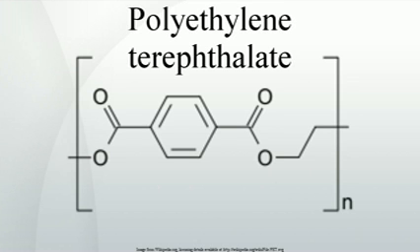Results are decreased reactivity during repolycondensation or re-SSP and broadening of the molecular weight distribution. The end group proportion shifts toward COOH end groups built up through thermal and oxidative degradation. The results are a decrease in reactivity and an increase in acid-autocatalytic decomposition during thermal treatment in the presence of humidity. The number of polyfunctional macromolecules increases.